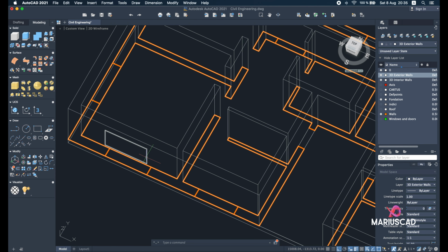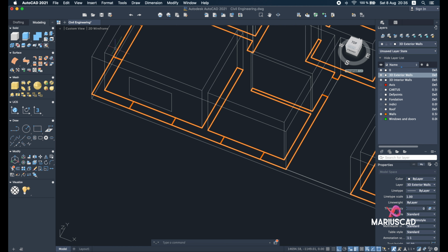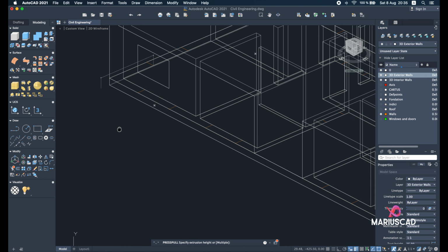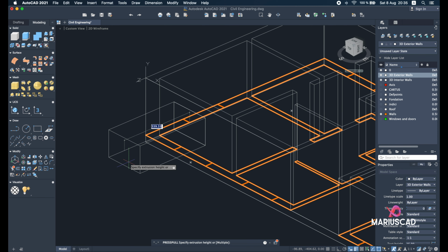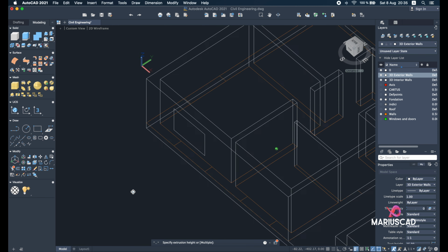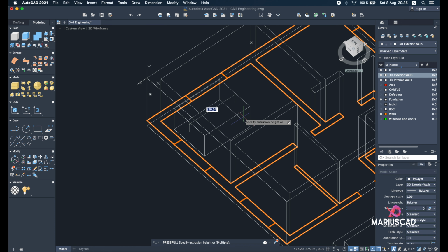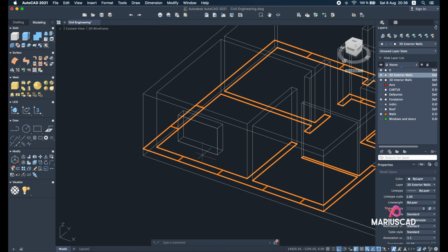This rectangle is located on an exterior wall. So when I apply press pull, make sure that it is the right plane. If I apply it on the exterior, it will be an additional, extra object. But if I go from the interior, it will be a hole, and you can see it automatically. I highly suggest sometimes saving the drawing, just in case.